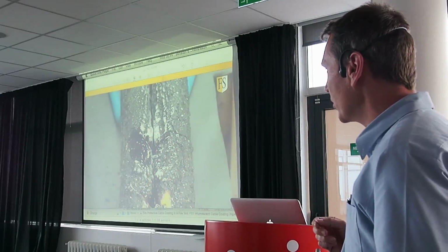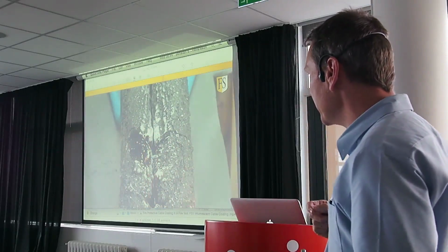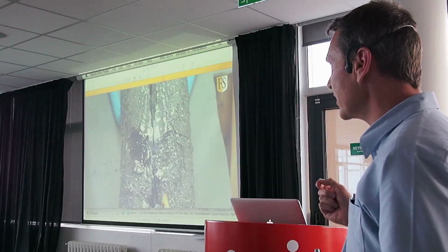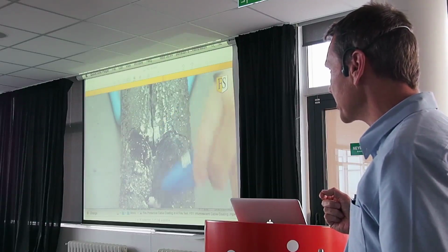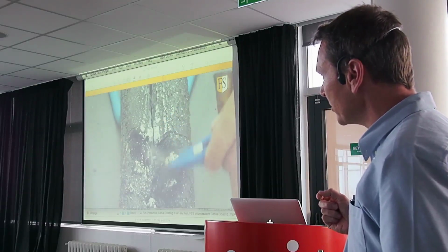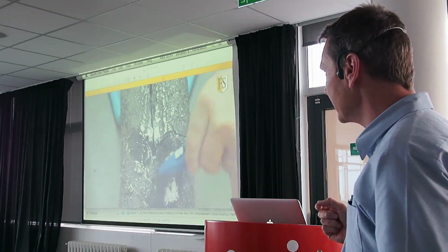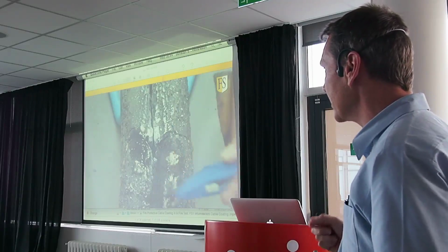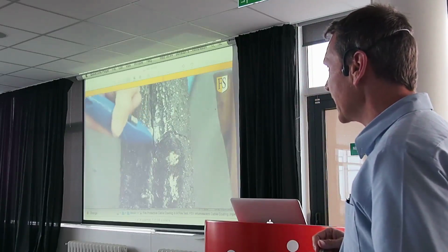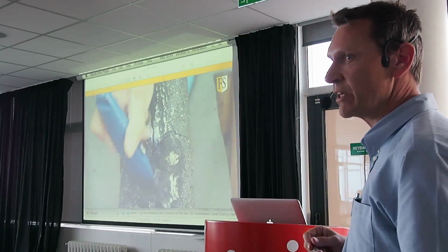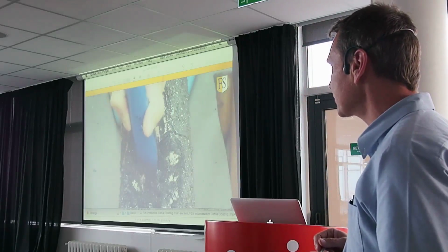So what it's showing is that once it's burning, we're scraping away, and this is only a 1 millimeter thickness coating. So it will expand. See, they're scraping it away. The coating is still there. It hasn't even yet been affected. So then they'll place it under flame again and again and again until you get to the actual cable substrate.